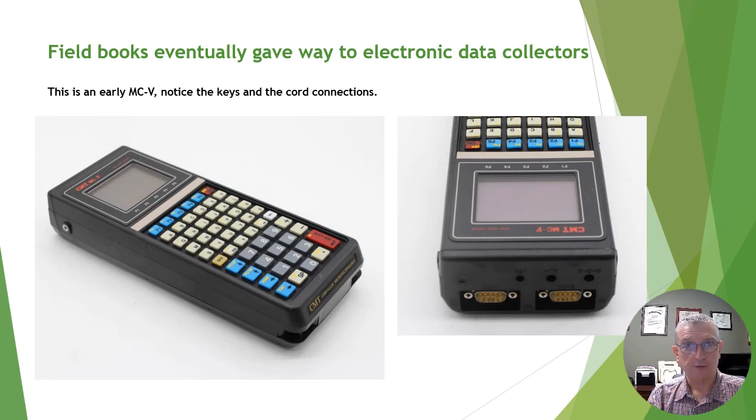They started using it on surveying instruments, so that instead of having to look through that peep sight and dial a vernier, the sine cosine encoders were wheels mounted to the plate of the instrument that could very precisely measure how far it rolled around. Some of the earlier ones actually had errors in that they would not measure exactly 360 to a circle. That's how they were calibrated: you would sight on an object and rotate the scope 360 degrees, and it needed to read 360. Some of the earlier ones did not.